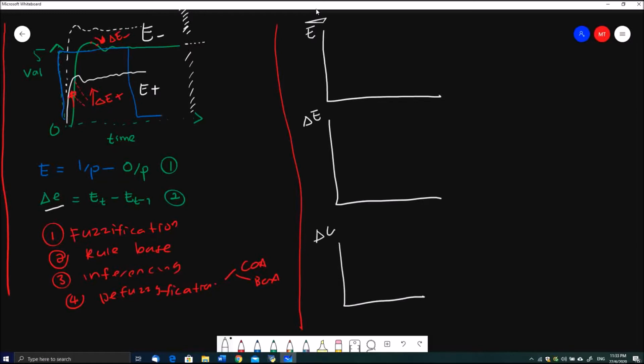will be delta U. So in the notation of the transient response, we have the error positive, error negative. So we can utilize that in order to generate our model here. So let's say we define 0, which is no change in terms of the error, and then the right side is the positive part, and the left side will be the negative part. So for the 0, we tap the value at the 0 location.